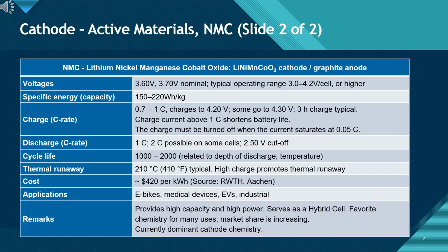As you work on the line, you will likely see more NMC cells than any other type, so understanding these general operating parameters, like the typical cycle life of 1000 to 2000 cycles, will help you spot quality issues if they arise. Take a moment later to review the specific voltage and thermal numbers in this table, as safety is always our priority.